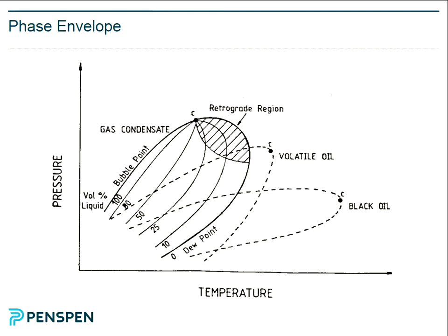So often in gas condensate systems, you're in this position of liquid dropping out. This is multi-phase flow. There are other terms you hear on this as well. There's the cricondenbar and the cricondentherm. The cricondenbar is a line across here. Basically, it's the pressure above which multi-phase flow won't exist, and the cricondentherm is the temperature above which multi-phase flow won't exist. So this can be bounded by these two lines, basically, cricondentherm and cricondenbar.